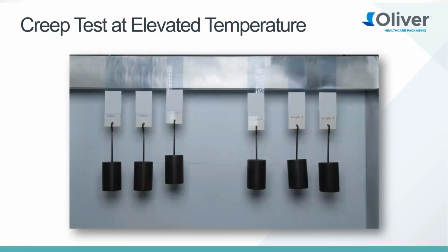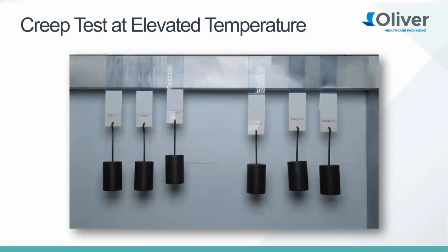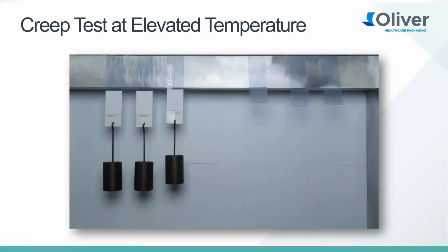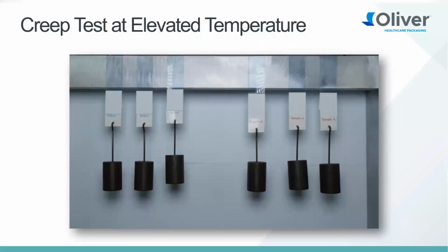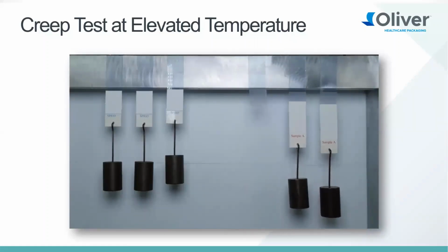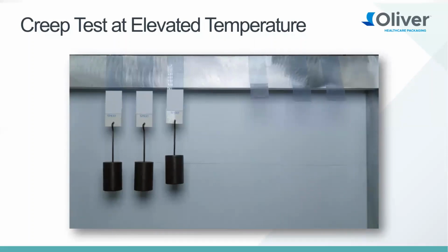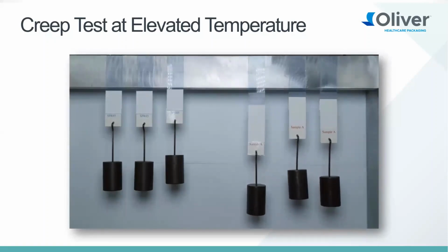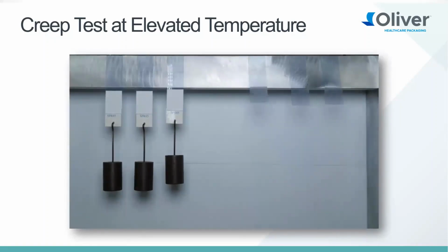So it's basically saying at 55 degrees Celsius, the coating on the left is maintaining strength better than the coating on the right. And again, not saying that the coating on the right is going to be problematic in all applications. It's just kind of highlighting that there are differences. And so the way I look at it is, all else being equal, why not have the insurance policy of a coating that's got very robust capabilities at high temperature or elevated temperature?